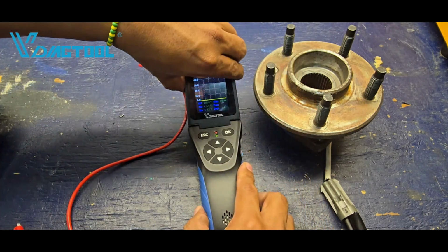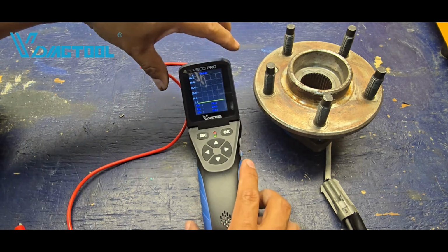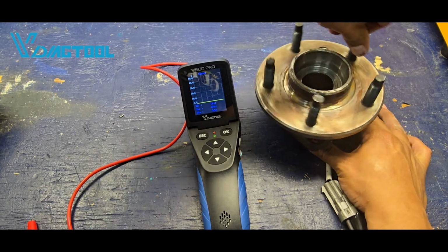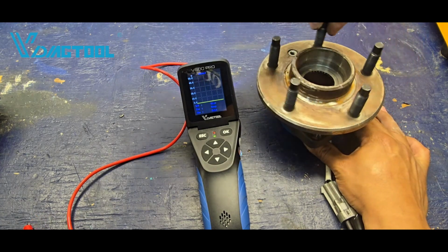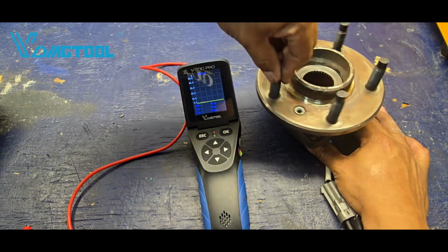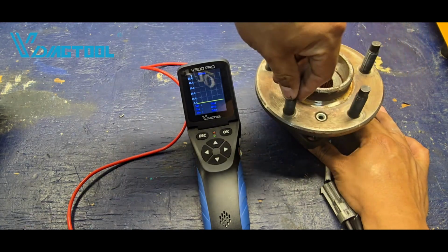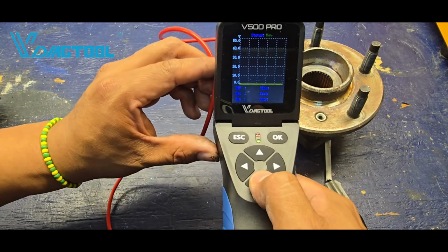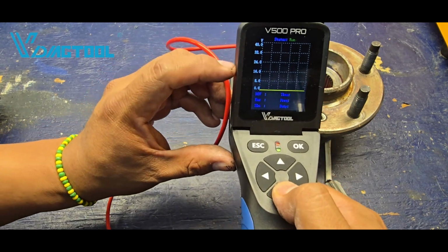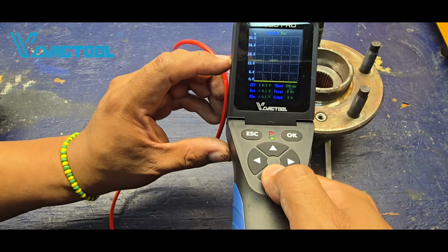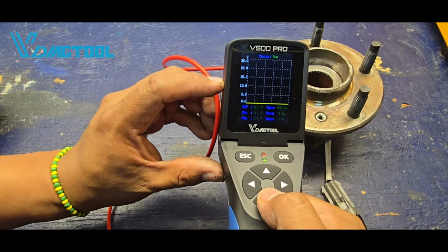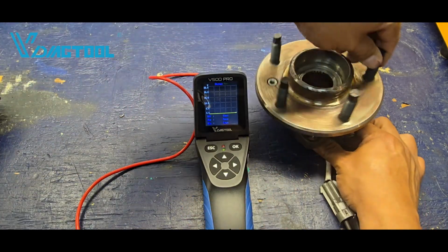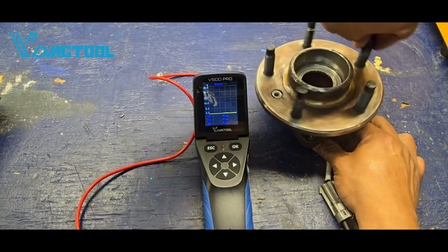If we rotate our screen so we can see this, and we spin that reluctor wheel, there's a little change on our screen, but very little, because our voltage value is too high. So if we bring this voltage value to maybe 5 volts per division, from 50 we bring it down to 25, and if we rotate, there's a slight change.